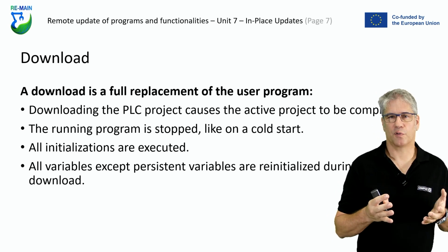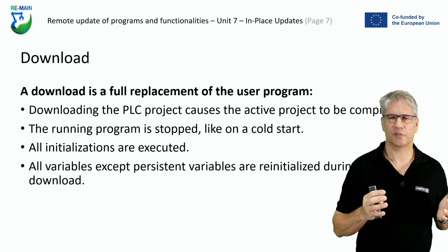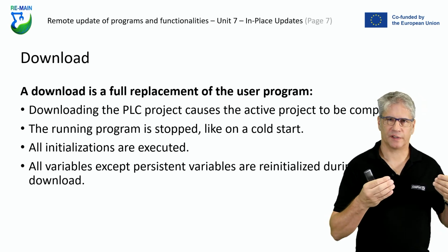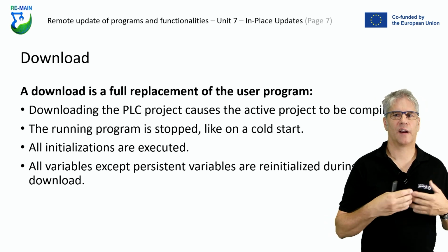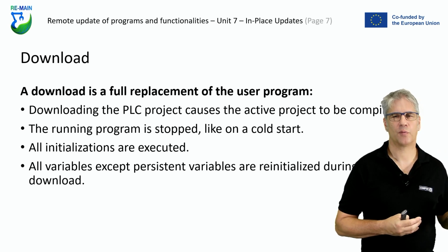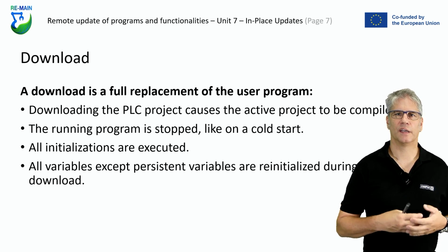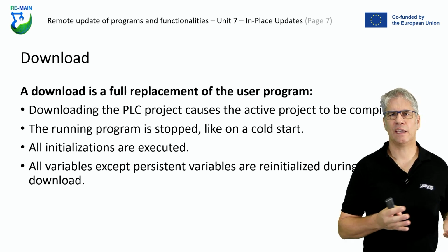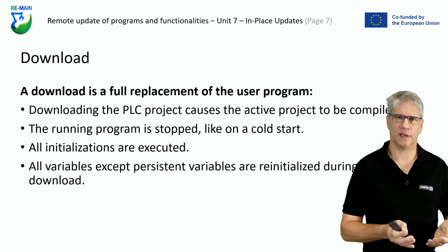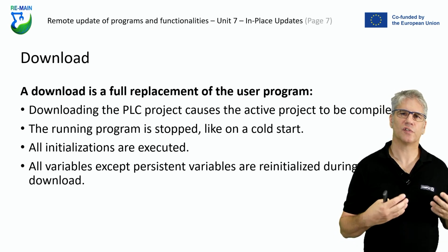The running project, of course, before it is deleted, will be stopped, like on a cold start. So total shutdown, not electrically, but in terms of software. And when you start again, all initializations are executed, which means if you have some init sequences, all this will be run through. Therefore, all variables, all parameters, all interfaces are initialized properly. If you have some persistent variables, retained variables, normally they are retained, so they are kept in the PLC as long as you just do a download.